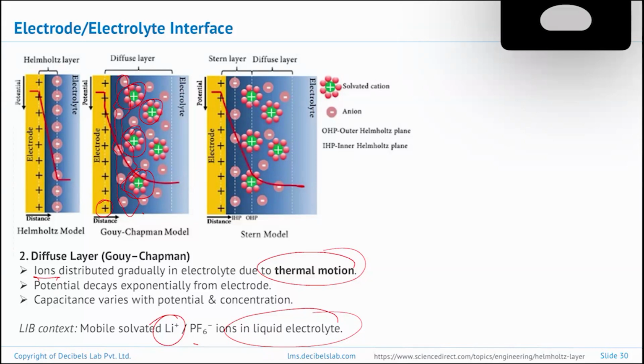When we charge a battery, lithium moves from the cathode to the anode and enters inside the graphite, right? So if you charge more, lithium enters and it may come out. Once it comes out, the lithium starts reacting with the electrolyte. As I showed you, lithium is highly metallic. After reducing, it starts reacting with the electrolyte and liberates gases, and it may lead to lithium plating or dendrite formation, and it starts growing and may hit the separator and come out from the separator and connect with the cathode, and that may lead to a short circuit.